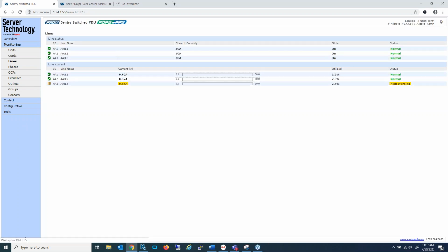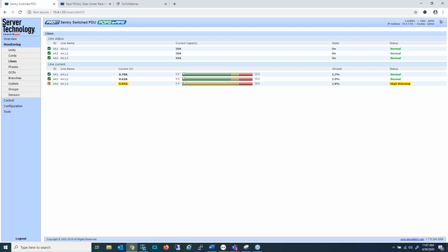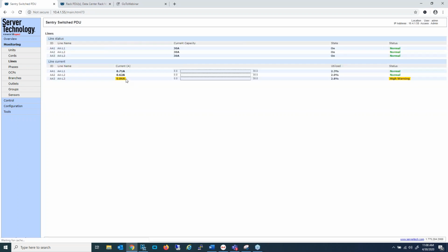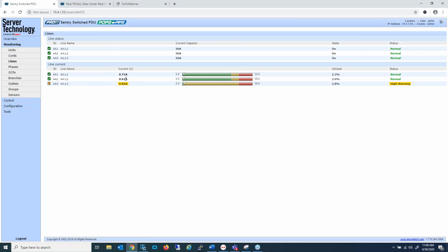Now in North America, I'm sure many of you are aware that we are only allowed to use a circuit continuously at 80% of maximum. So as we'll see when we take a look at some thresholds, the thresholds are actually not the maximum value. It's also recommended, though not necessarily mandated, that you use only 80% outside of North America, but it is typically recommended as best practice.